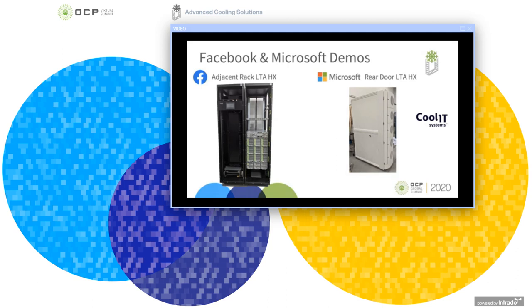On the right-hand side is the rather sharp-looking Rack DLC AHX40 in Project Olympus White. This is a modular solution comprised of the RPU, a blind mate vertical rack manifold, and a 40 kilowatt active rear door heat exchanger. The bottom 4U are occupied by the RPU. It has blind mate power and liquid connections, and there are 5 efficient 280 millimeter fans with N+1 redundancy. In this solution, the target approach temperature is 12 degrees C with a 40 kilowatt load. With that, I'll pass this back to Sam for a comparison between the two solutions.